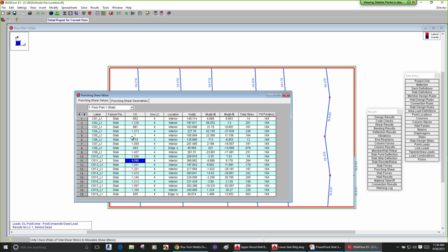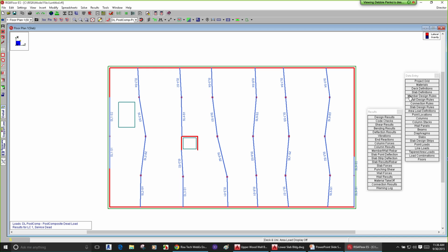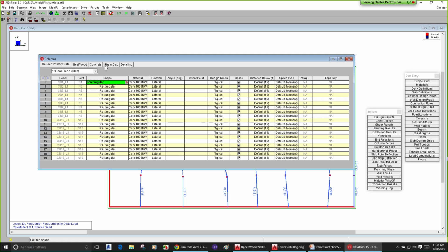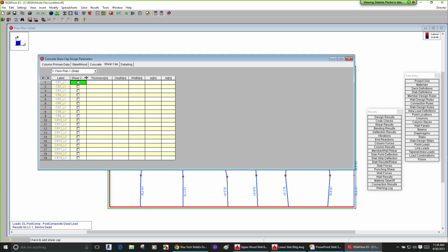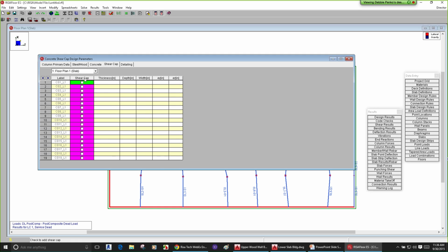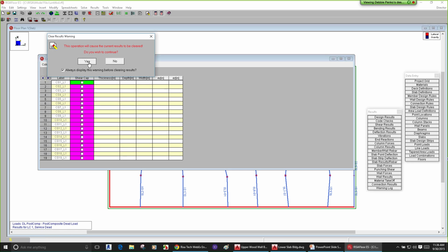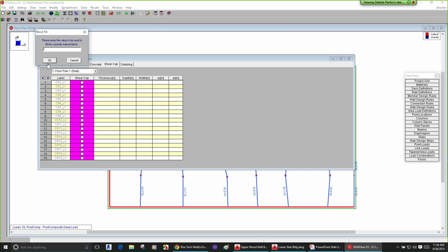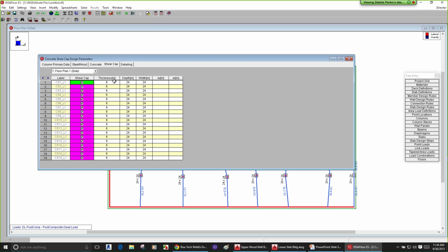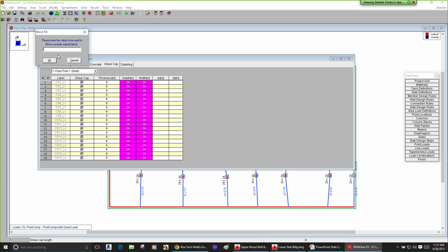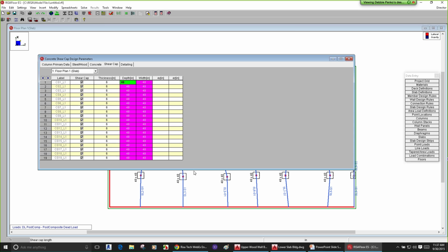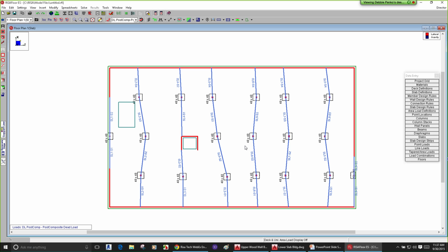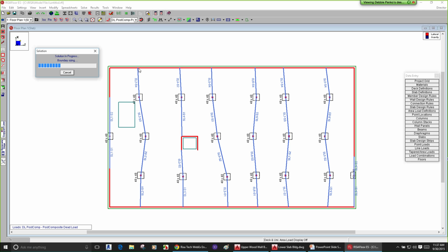You might say, hey, you can just thicken the entire slab, but maybe it's cheaper, depending on where you live, for you to build a shear cap. Maybe that's more. If you want, you can do shear caps here. All you have to do is just add a shear cap. I'm going to say fill the whole block, add shear caps on every column. That's definitely a question you have to ask yourself, is that worth it? But let's just see, I can do a 48 by 48 shear cap of 6 inches extra. So it's not a lot, but it might get us past all those problems with the punching shear.